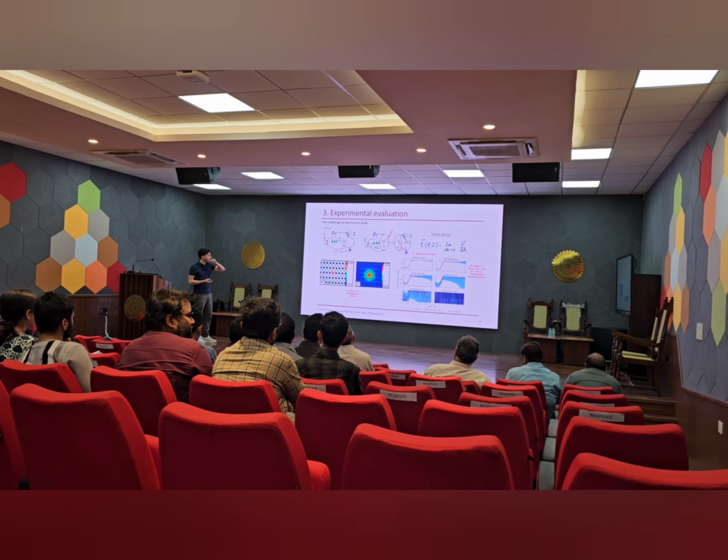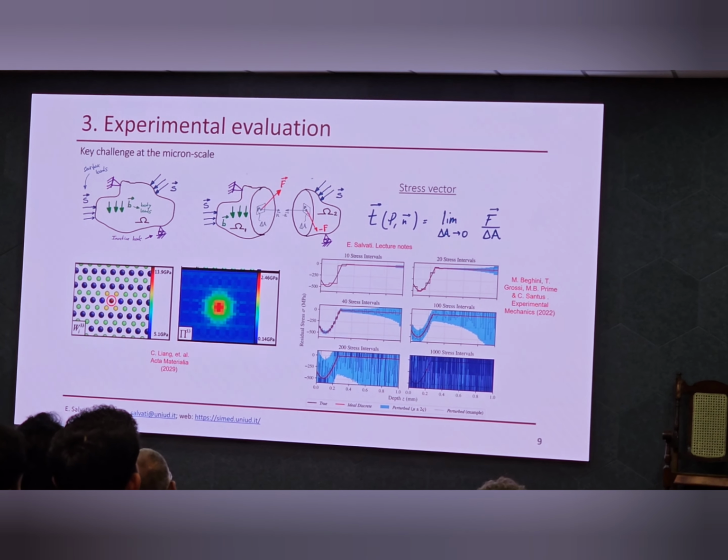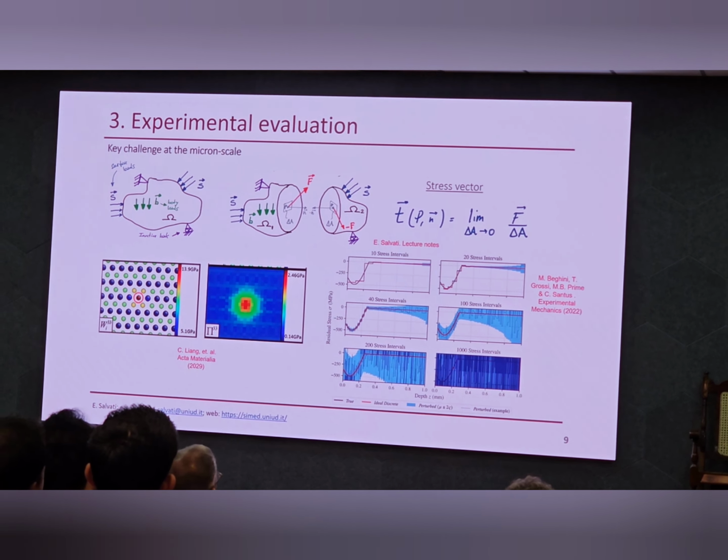So another nice recent paper from some people in Italy and US where they try to resolve residual stress in depth using some regularization methods, and they end up saying that if your regularization, I'm talking about 1 by 1 millimeters, you can resolve single grains and you can resolve type 2 residual stress as well with this technique, which is super powerful and has been developed very recently.